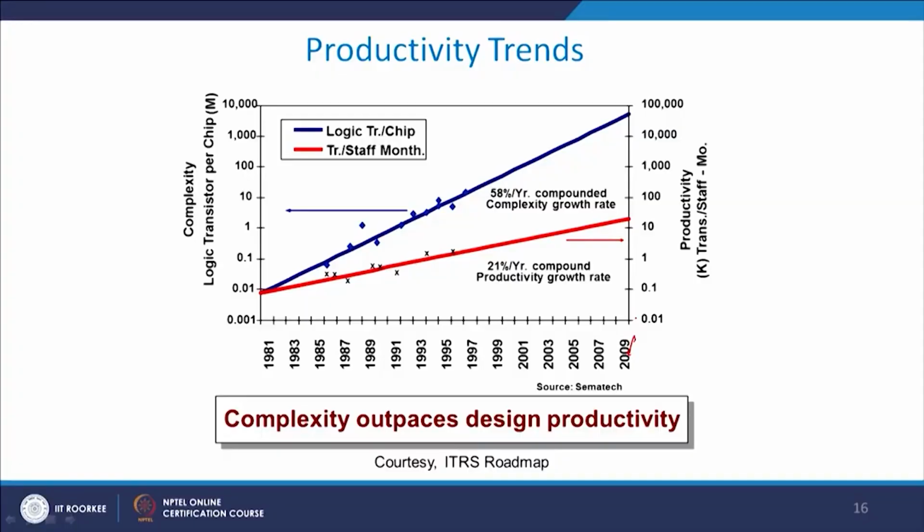Generally, clean rooms are marked as 10, 100, 1000, 10,000, and so on. 10 is basically the best one, because there is a small number of particles per unit volume of that area, while 10,000 will have many more particles. So, the lower the value, the higher the cost, both running cost and the cost of fabricating a clean room environment. This is a typical environment you get in a clean room.